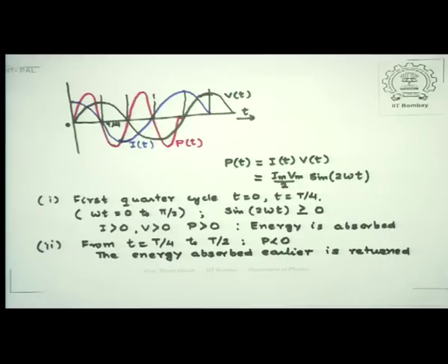So what we have done in this lecture is to talk about a circuit which consists of a source of an alternating voltage with a capacitive element put in there. We found out that in a purely capacitive circuit, the current leads the voltage by an amount of pi by 2, and we discussed how a purely capacitive circuit can be used for purposes such as being applied as a voltage divider and things like that.